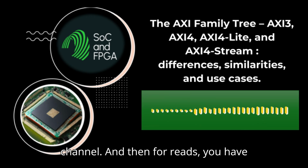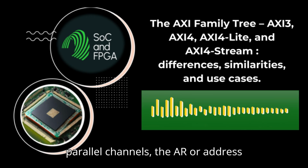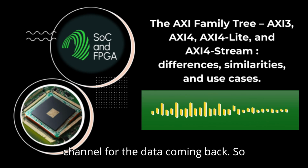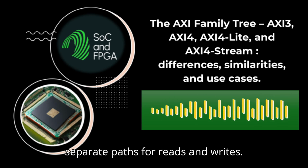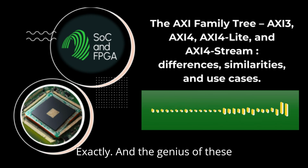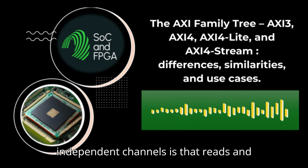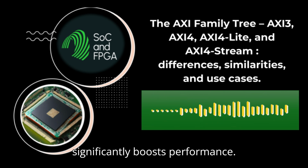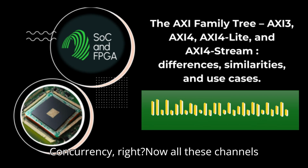And then for reads, you have parallel channels. The AR, or address read channel, and the R, or read data channel for the data coming back. So separate paths for reads and writes. Exactly. And the genius of these independent channels is that reads and writes can happen simultaneously. That significantly boosts performance. Concurrency.